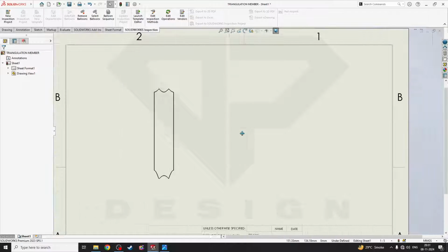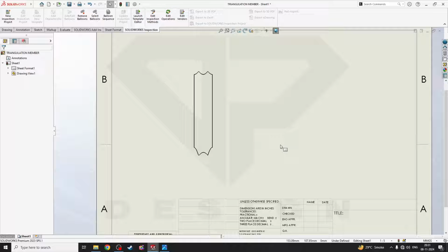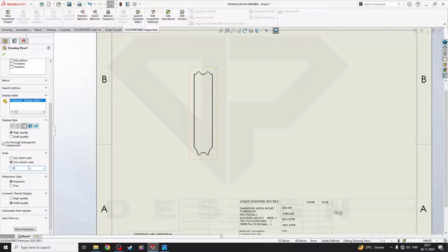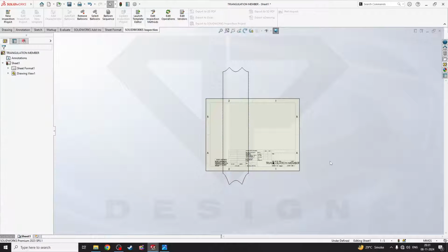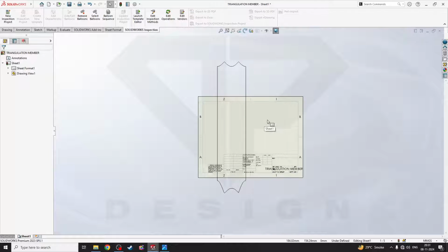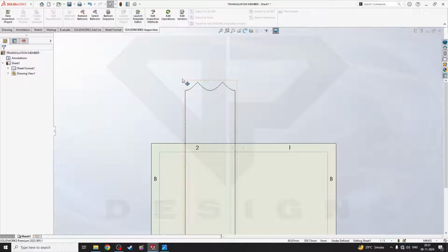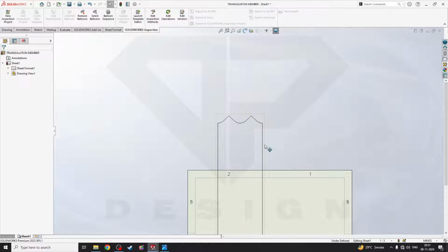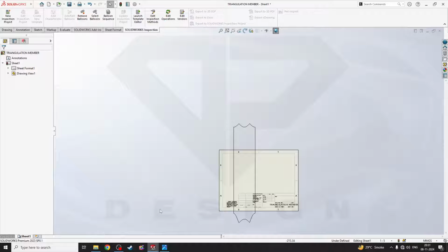Now in a single drawing, whatever members are possible in 1:1 scale, you don't have to scale it down. Make sure it is not scaled. Use custom scale, and here you have to give 1:1, and select the paper size accordingly. We have taken a very large paper for this and taken out so many members together, so that there is no difficulty in cutting this area. You have to cut this, and just clip it on the member. That's how you can make a perfect notch.